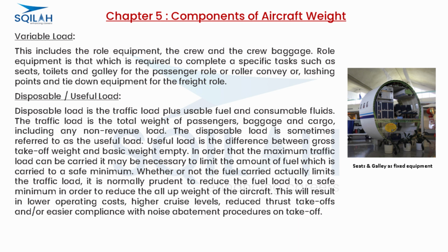In order that the maximum traffic load can be carried, it may be necessary to limit the amount of fuel which is carried to a safe minimum. Whether or not the fuel carried actually limits the traffic load, it is normally prudent to reduce the fuel load to a safe minimum in order to reduce the all-up weight of the aircraft. This will result in lower operating costs, higher cruise levels, reduced thrust takeoffs, and/or easier compliance with noise abatement procedures on takeoff.